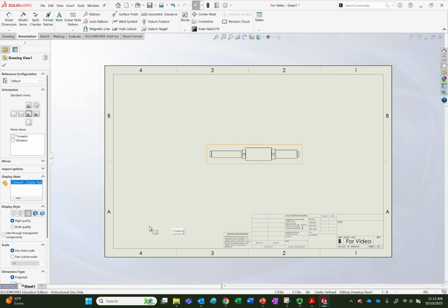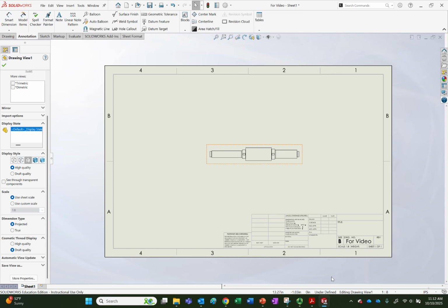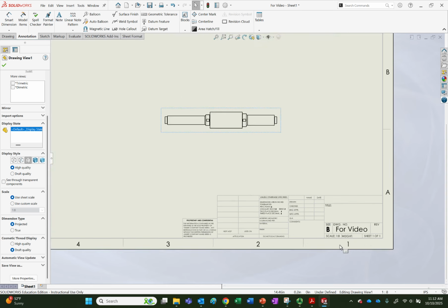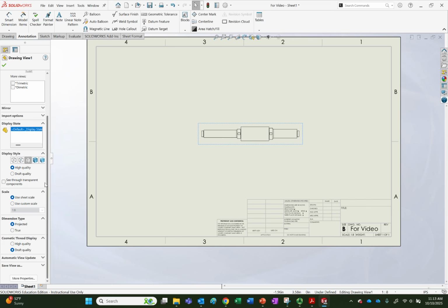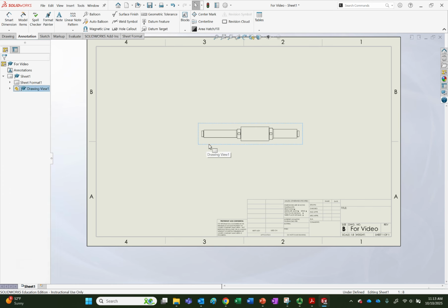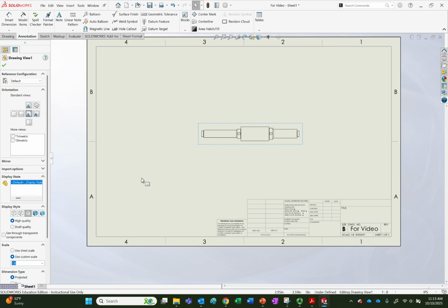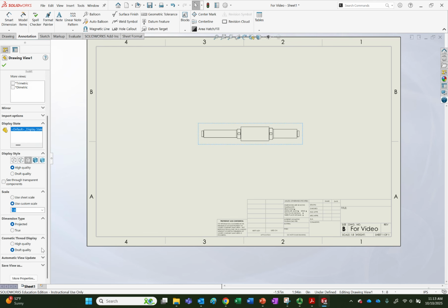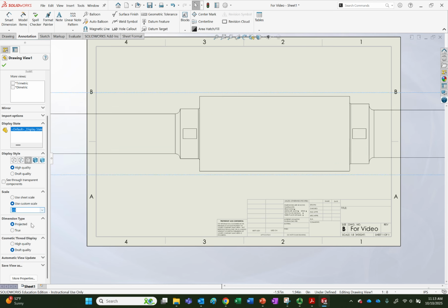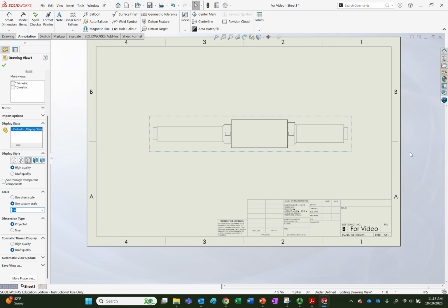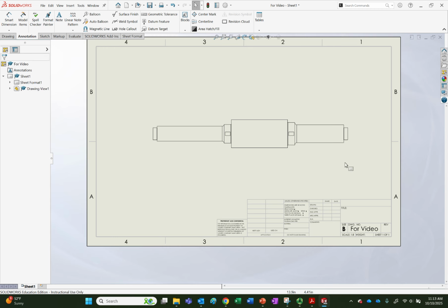Now we are not using our space. For whatever reason, the sheet decided to go 1/8 scale by default. Let's use a custom scale. By the way, I clicked on the outside little guy right there. That's what brings this up. And we're going to try out the different scales. Can we go to one size large? That's actually not too bad. This is a weird scale. Nobody wants to do 2 to 3. So I think 1 to 4 is about the best we're going to do in terms of a sensible one.